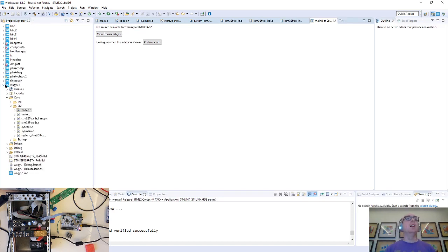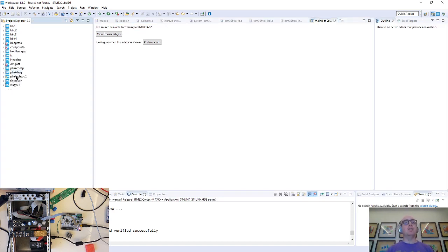This is STM32, and these are all of the various things I've brought up on this laptop. There are so many bugs. For a long time, for example, it would generate mistakes where it wouldn't generate the DMA initialization in the right order, so your DMA silently wouldn't work. And it wouldn't open old projects. Every now and then they upgrade it and then it won't load old projects. It wouldn't load a project for my Mac. It would just hang forever. So I ended up just creating new ones. And sometimes mysteriously stuff would just stop working. So I just do file new project a lot.